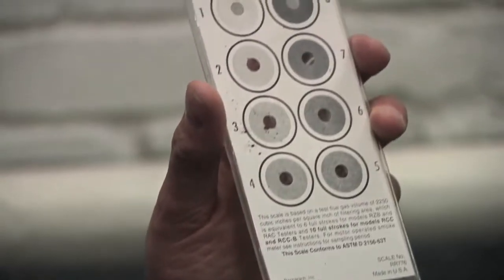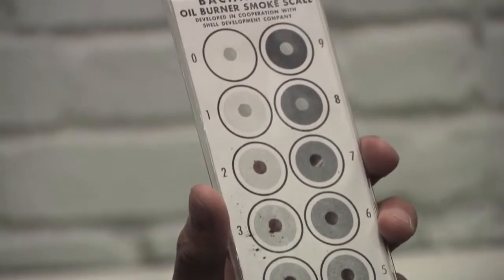So what happens if I get a 9? If you get a 9 or anything really high, you cannot test. It's going to clog up the analyzer. It's going to kill the pump, the pump inside the analyzer, right. So it's going to get in. If it bypasses this filter, especially if you have a lot of it, it'll get past it. And some of the older models that didn't have this filter, you can really damage this piece of equipment. Right. The tubing inside here that connects to that pump is a very small diameter, 16th of an inch diameter tubing. So if you get any little bit of particles inside there, they'll build up and then they will cause the pump to fail or cause a blockage inside the tubing.